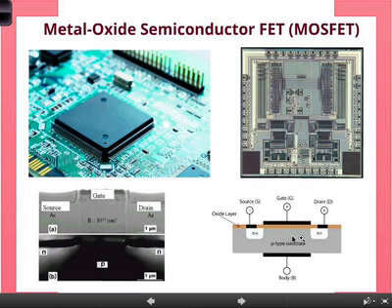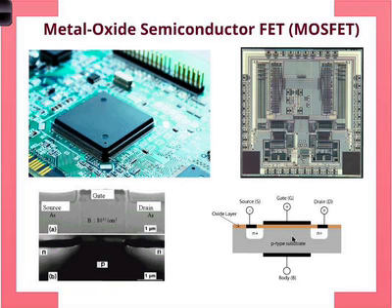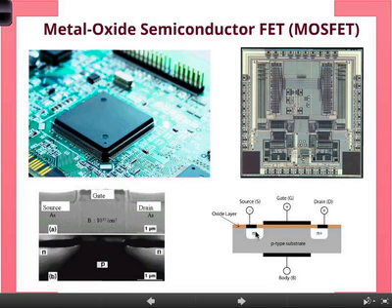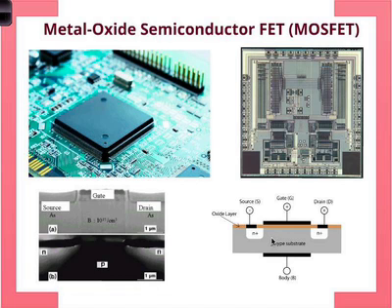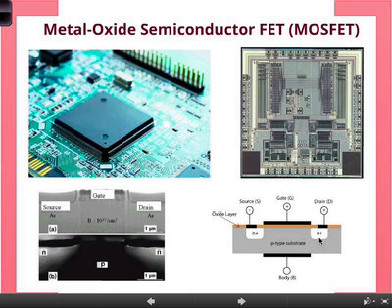Okay? And of course, if you look at this and do not apply any voltage, we know that this is an N+P junction, so you have a contact potential there, right? So there's an electronic barrier for the majority carriers, electrons, to go from here to here. Remember, there's a contact potential or barrier. So nothing happens, right? No electron flow happens. Same thing over here. You will see a barrier going from this way to this way, symmetric. Now, applying a gate voltage is not going to change that quite yet. Now, we'll talk about what happens.